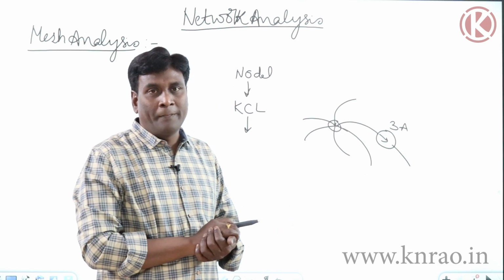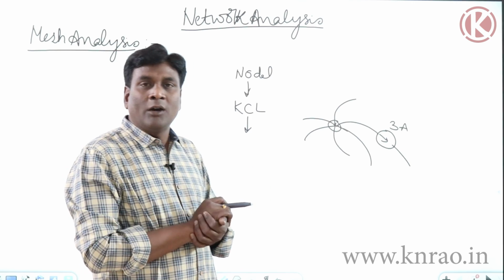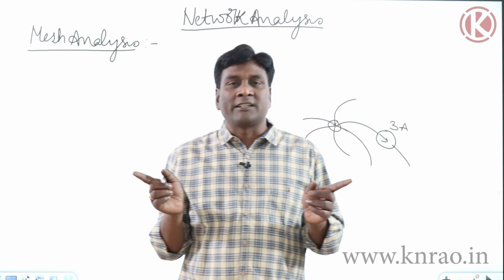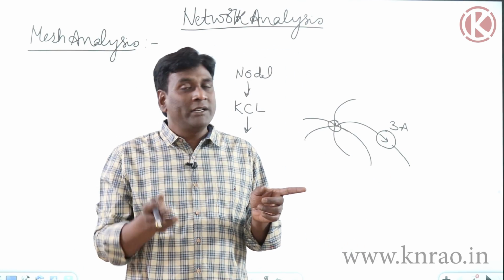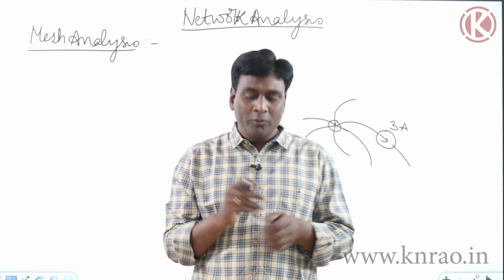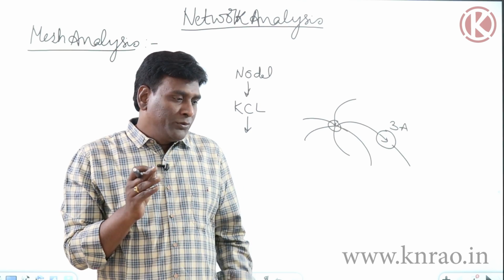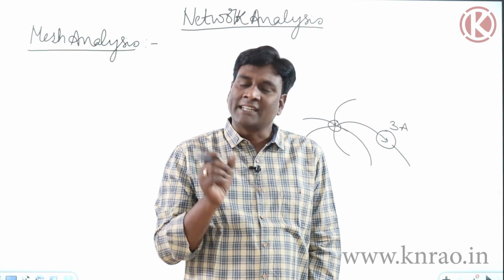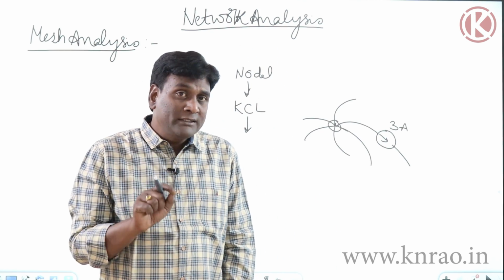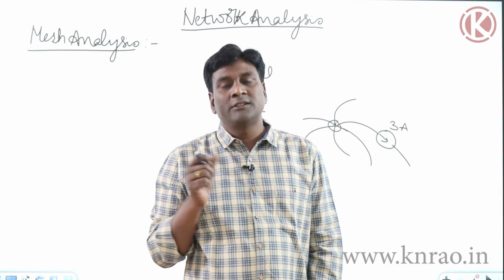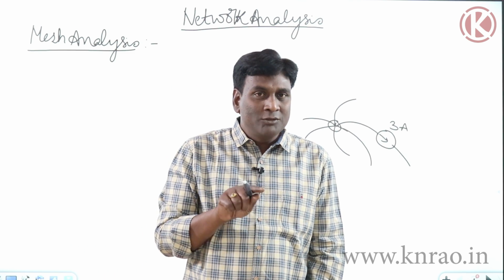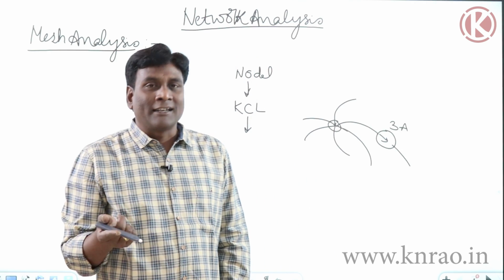the current source is known. Basically, one thing we have to understand about passive elements and active elements. In passive elements, from currents voltage can be found, and from voltages currents can be found, because there is a definite interrelationship between voltage and current. Now if you think of active elements, for a voltage source voltage is known but current will be decided by the connected circuit. For a current source current is known but voltage will be decided by the connected circuit.